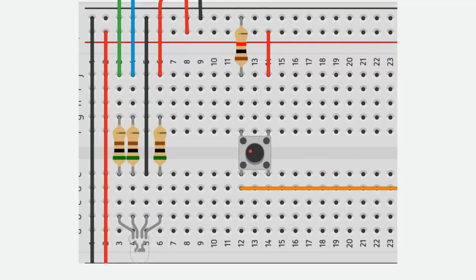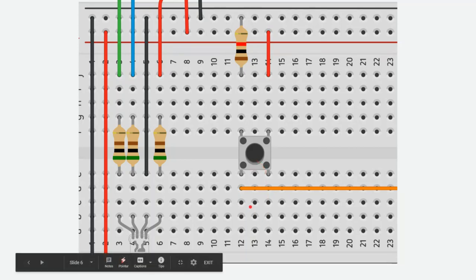So when it's not pressed, we're going to be connected to ground through here and through the resistor into ground. However, when the button is pressed, the power is going to flow into here, and since now these two are connected, it's going to connect into here, and since these two are always connected, it kind of makes this shape over here and connects to our input, and that way we're going to get our 5 volts when it's pressed and 0 volts or low when it's not pressed.